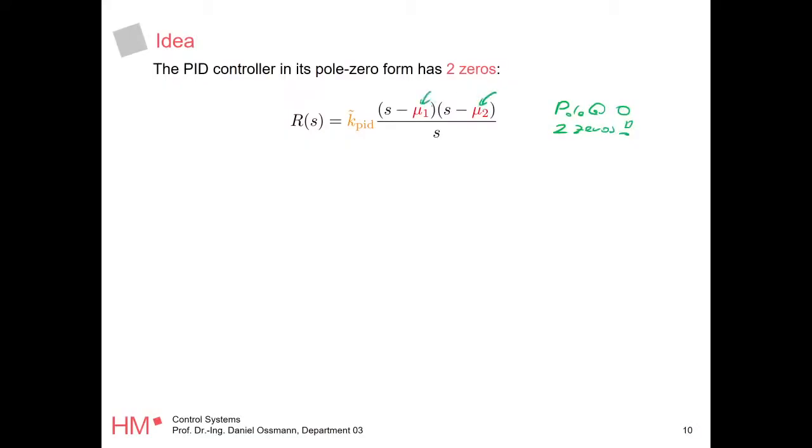So we are now moving away from that form that we have, Kp, Ki, Kd. We are now going to use more the form that we have two zeros and a control gain, right? But ultimately it's the same strategy. You can either tune Ki, Kd, and Kp, or you can tune your Kpid and your two zeros, right?